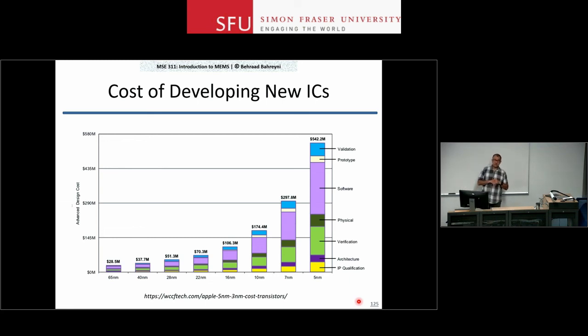Another thing you can do is that you go and make the chip and you see that it is failing the specs that you wanted, but it is meeting slightly lower specs. So let's say you design a processor to work at 3.8 gigahertz, and it fails the test at 3.8 gigahertz, but it passes the test if you drop the frequency to 3.2, 3.4. So you sell it under a different name, different chip number, but at a reduced clock frequency. And you obviously have to put your word behind it. Right? You have to guarantee that it is going to work fine.